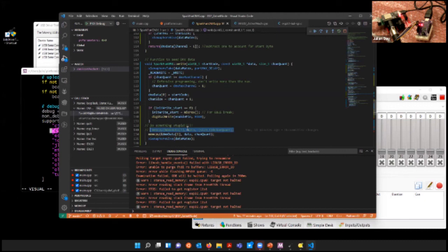The debugger was smart enough to know that the exception was associated with this task. So looking at the call stacks, I could relatively easily look up and ask what my program was doing at the point when this crashed. Because I deliberately put the bug in there, it's a trivial one, and it was obvious it was my silliness. If it was something going wrong in FreeRTOS, then I'd have to install the sources for FreeRTOS and start poking around in what it's doing. But this was a simple example, so relatively easy for me to sort out. Yeah, I understand. Okay. Thanks.